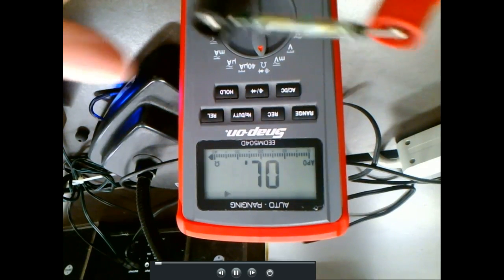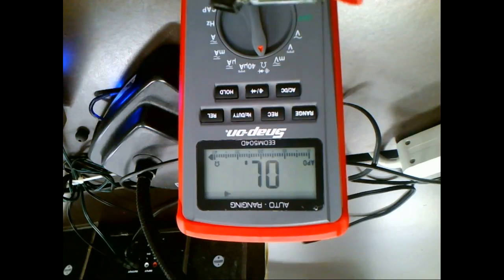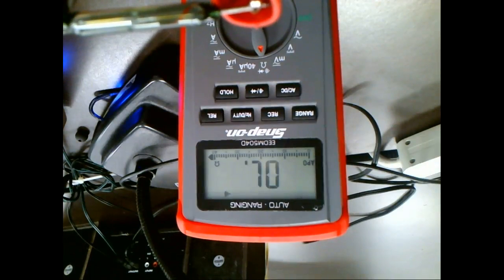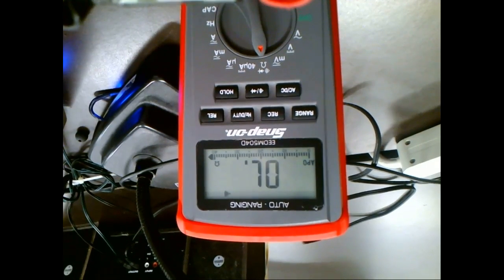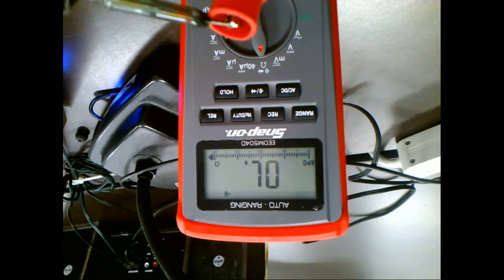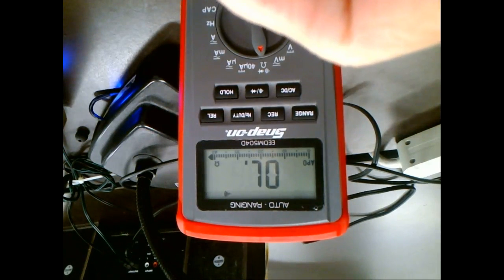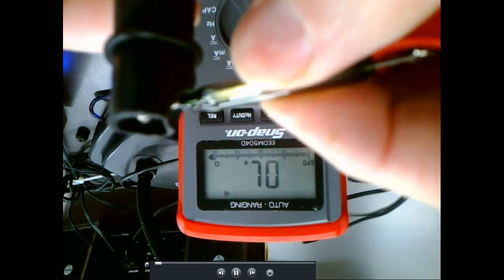Like I said, you can get them big. How big they are would depend on how much current they control. Switches, contacts and fuses are rated with two things. What are the two things we rate those by? Amps, and what's the other? Volts. The volts is the push, and we're trying to break a circuit. So the further we spread those contacts, the more voltage it can break, right? The closer they're together, the less voltage we can break, because if you create an arc, you get ozone and they'll start arcing. And we're also rated in current, so the bigger these rods are, the more current they can handle.